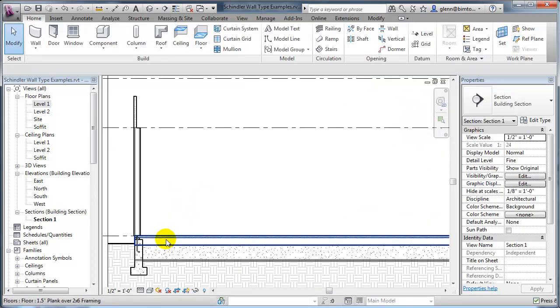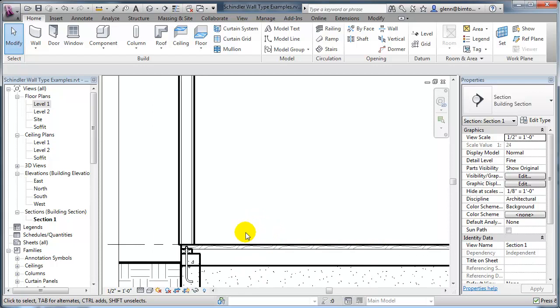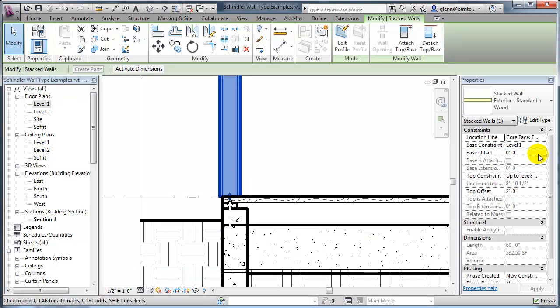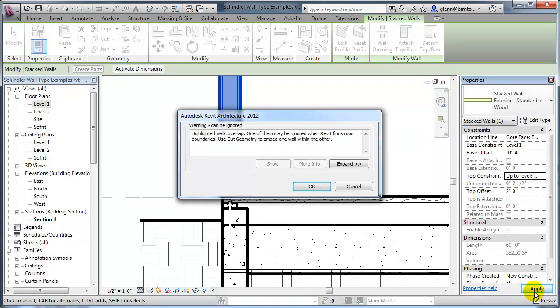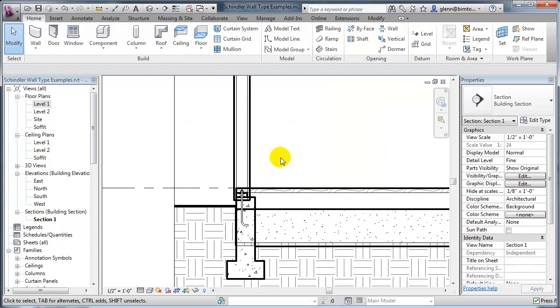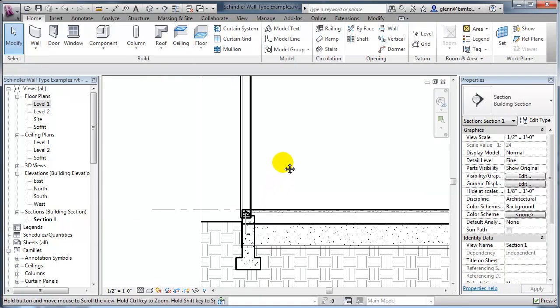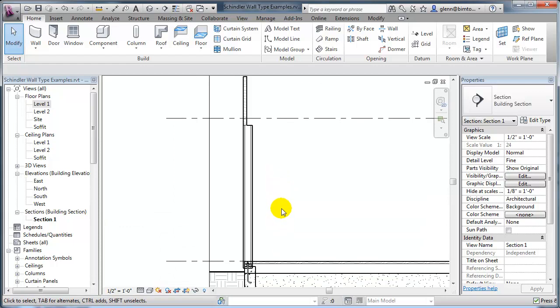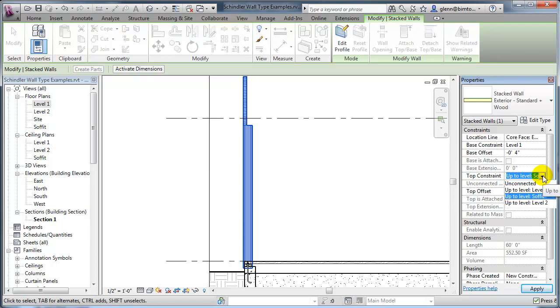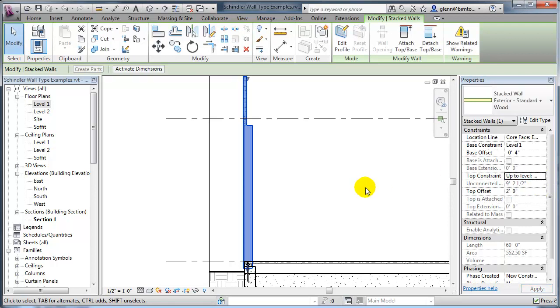So what's happening over on this side? We again have our issue of the walls looking pretty good. We might go ahead and wrap that down at the bottom, say -4 inches again. And it's warning us a little bit about all that overlapping geometry. It sort of knows that's something that'll have to be cleaned up later. But notice, this is sort of interesting. It's a little bit off. I wonder if it's because of the order of operations, because I do want it to be up to level soffit +2.